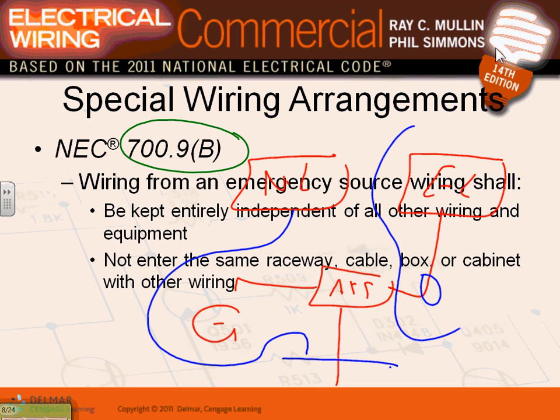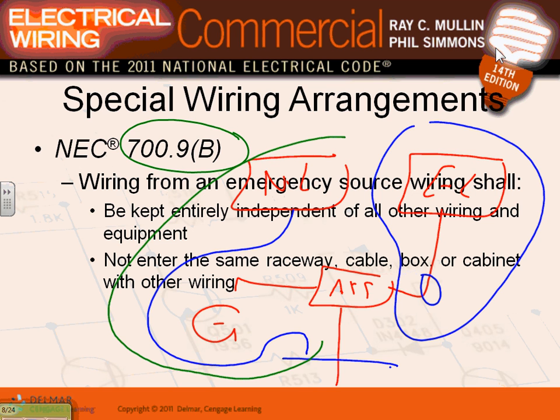This system here is my emergency system. It has to be completely independent of the normal system. This one here, all the way, is my normal system. So, long story short, Chris, I can't put this circuit and this circuit in the same conduit. These two circuits require separation of circuits.